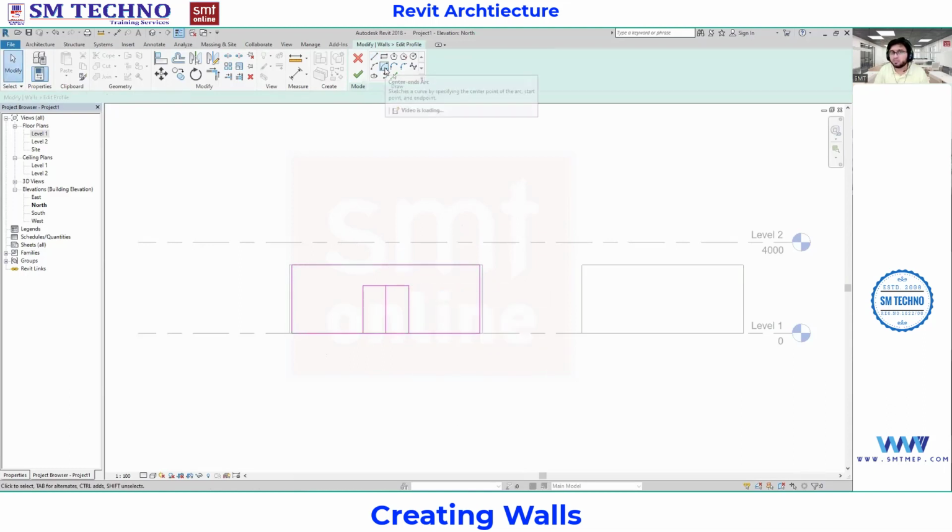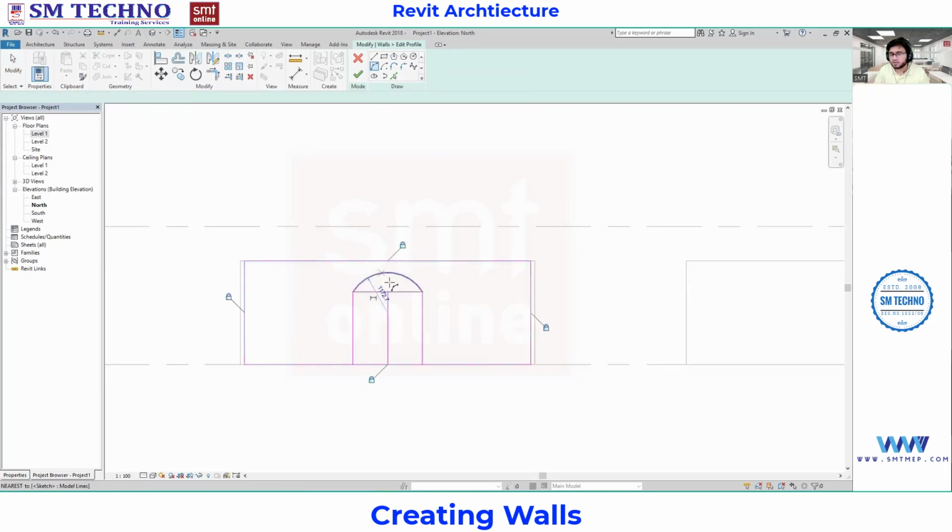Now go with the 3-point option, the arc option. So start, end point, and the midpoint. This is the starting point, this is the ending point, and this is the arc. Right click cancel, right click cancel. Now we are going to remove this because this was a reference line, so that exactly on the center of the wall it should be. I'll delete this, and delete this.